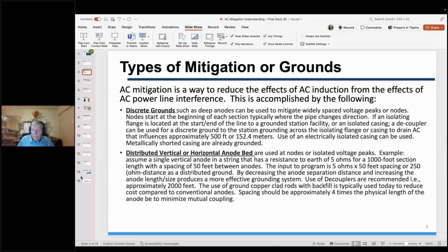The thing about the AC power toolbox mitigation is that you could create multiple scenarios in minutes to see which is most effective, whether it's ground rods, using a linear placement wire, or whatever method, and go back and forth and determine the optimum spacing, the optimum resistance, and the optimum cost of installing these.